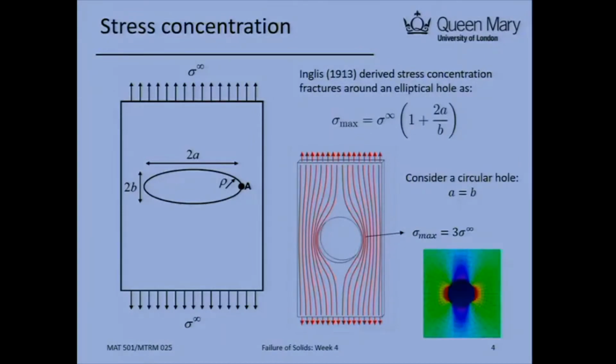Okay? So that's the relation for the circular hole. If you do some finite element calculation, you can see this part undergoes a very huge tensile stress. These two are basically under tensile loading if you draw that. And this part, because of the Poisson ratio effect, some of the material is under compressive loading from here and from here. So that's why you have a compressive stress.